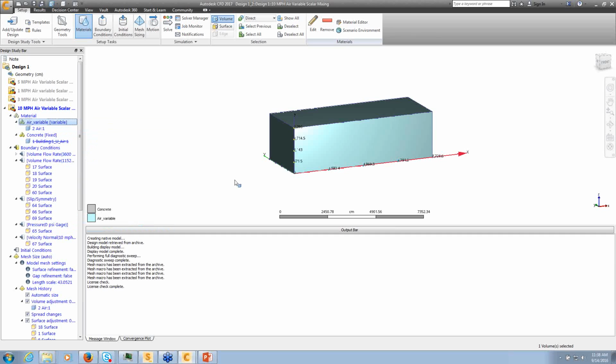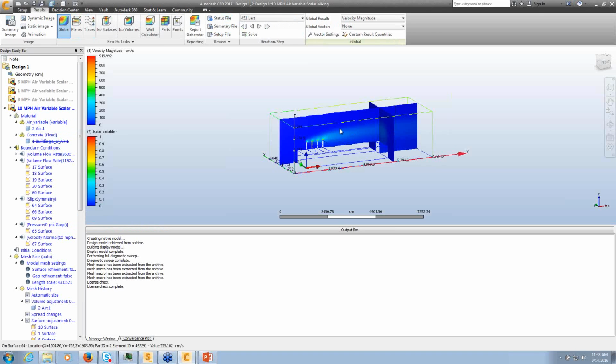So let's say the density in this case changes quite a bit. The air coming out of those stacks is very heavy. Then there's going to be more of a chance for it to come down and go into the inlet. Whereas if it's light, it might not present as big a problem for it coming back into the building. Very good point, Amal. Thanks. You're welcome. It was very interesting.